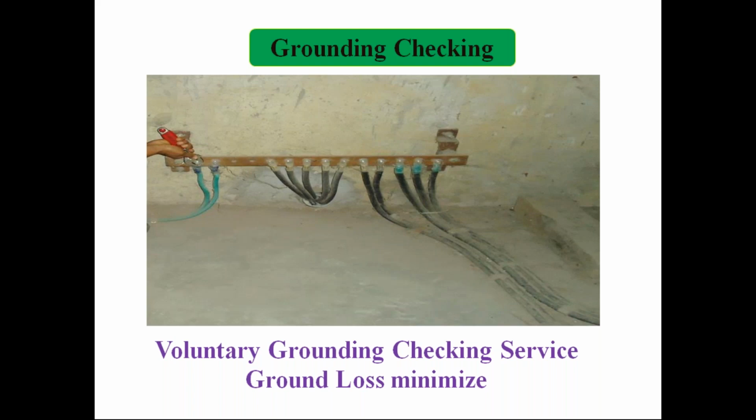Again, the other way I will say, what were the losses to the utility? For 80% power factor, if we have got 1000 kVA at our substation, the customer is billed 800 kilowatt hour for 1 hour consumption. But with power factor 95%, we are getting a bill of 950 kilowatt hour. So with 80% power factor, the utility is going to get 150 kilowatt hour less bill, only for 1 hour.